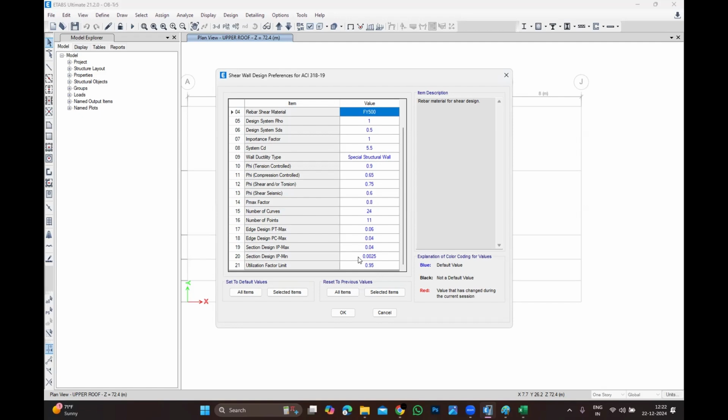They'll ask us to, like, this will help you because if it has failed in the 5%, then it won't fail. You're getting a point. What I'm trying to say is that now you are limiting to 95%. You are only using 95% of the capacity of the structural element. You are not using 100%. You are keeping a 5% cushion. You don't need it. First of all, you need to understand: don't be afraid. You have material factors. You have load combinations on top of the factor of safety. On top of it, you don't need anything.